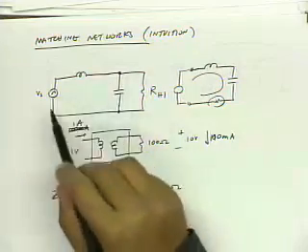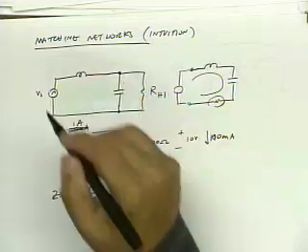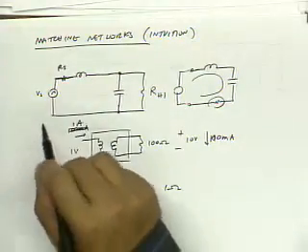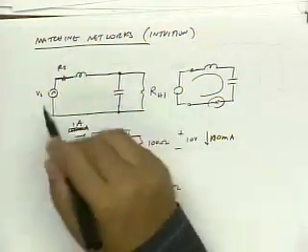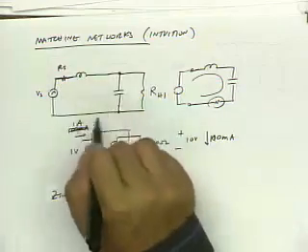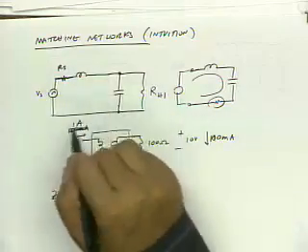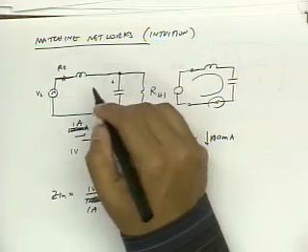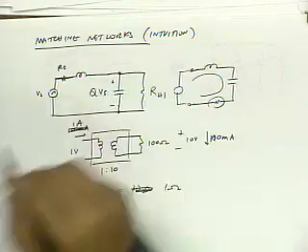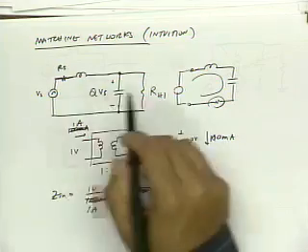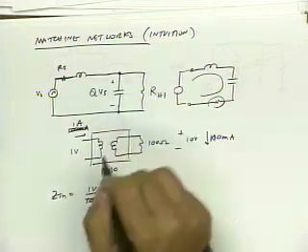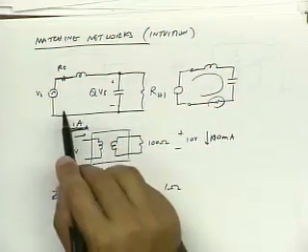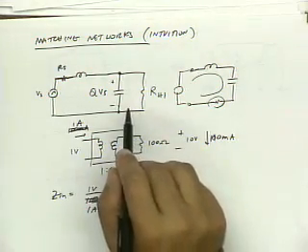So in this circuit, what happens is, if I drive this with some source resistance RS, then at resonance, if this is designed to be a matched circuit, the current is just Vs over 2Rs, right? But the voltage across the reactances is Q times Vs, right? And that means that because I have a voltage multiplication, I have the same current multiplication in the other direction.